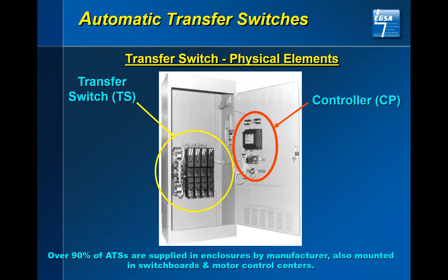Pushing on a little bit more, again, looking at a contactor type transfer switch. On the left side, you will see the transfer switch mechanism. Notice two things. Number one, if you can see it, those silver are the lugs. You will notice that there are two of them facing up and one of them facing bottom. One of the top is typically the emergency or the normal. The other one down at the bottom is the normal or the emergency. The middle one is the load.